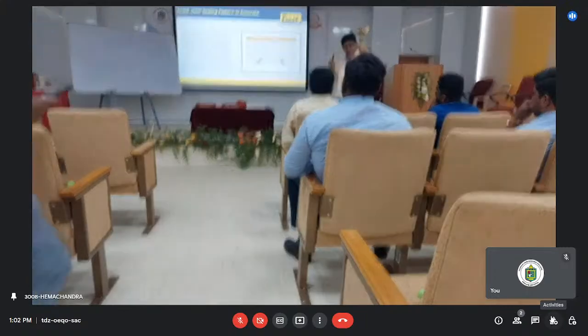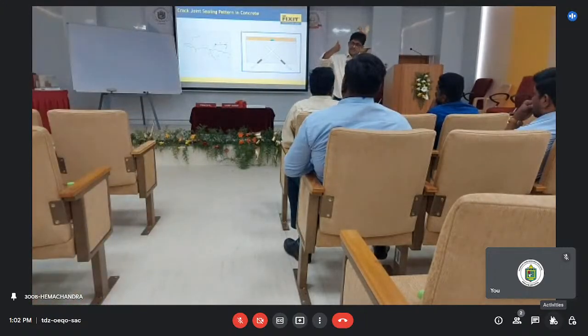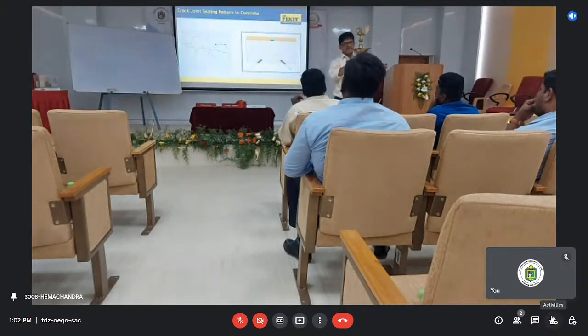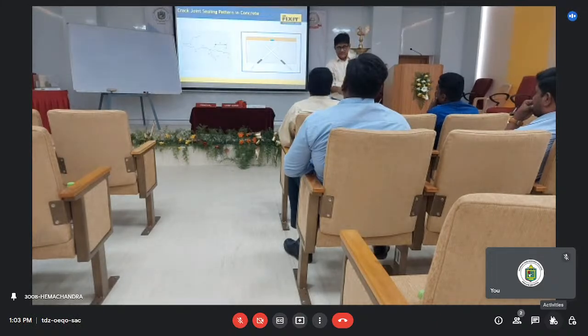When the top crack happens, how does the stress go? The stress may be because of load or anything. That stress from the surface goes into the concrete matrix. Now in the matrix, what breaks first? The first weak link is your aggregate and the cement paste, the weakest link inside the concrete. That link will not be on the same mapping, so it can go like that. Unless you do both sides, you cannot map it. So you have to take both sides.